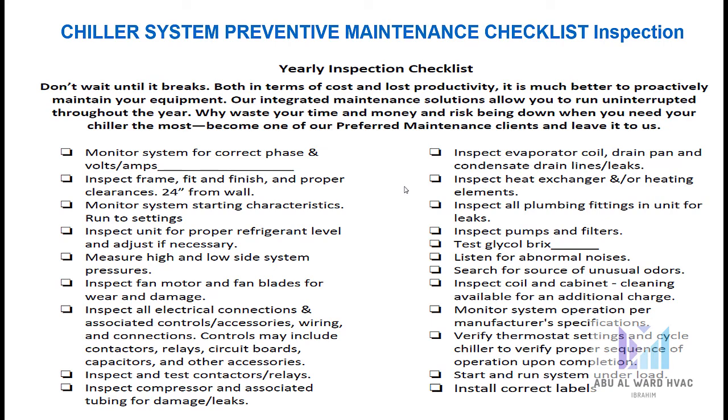inspect all test contactors, relays as well, inspect compressor and associated tubing for damages and leaks, inspect evaporator coil, drain pan and condensate drain line leaks, inspect heat exchanger or heating elements, inspect all plumbing fittings in unit for leaks, inspect pumps and filters, test glycol, listen to abnormal noises, search for source of unusual odors, inspect coil and cabinet